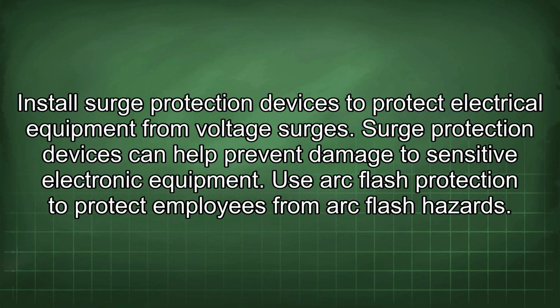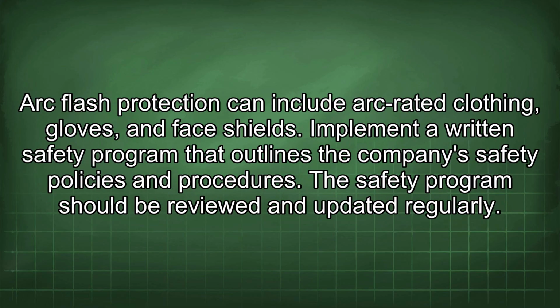Install surge protection devices to protect electrical equipment from voltage surges. Surge protection devices can help prevent damage to sensitive electronic equipment. Use arc flash protection to protect employees from arc flash hazards. Arc flash protection can include arc-rated clothing, gloves, and face shields.